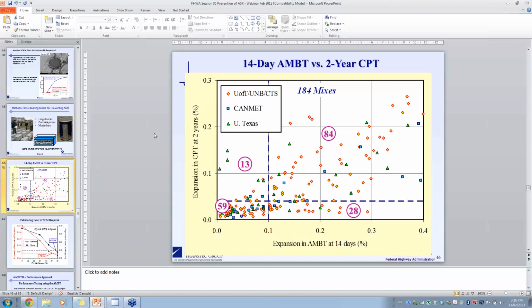Mixing it with soil, I'm not sure I'd want to mix it with soil to make a base, but using recycled ASR affected concrete as a base is unlikely to produce expansion of that base because you've got so much void space in there. But it's really something that hasn't been looked at to any significant extent. I would expect it not to.